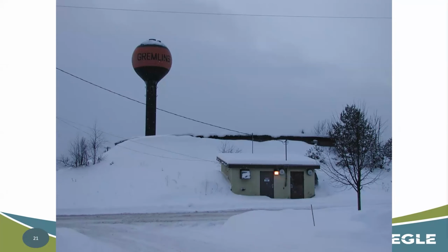Okay, so this is actually 2 combinations here. You have your elevated storage tank up here. This is a 50,000 gallon versus your 750,000 gallon right here. You can kind of see it, it's all covered in snow, obviously, but this is kind of doing the best of both worlds here. So it's maintaining that pressure if need be, but then you also have a large volume there if you ever need to meet those peak demands, or maybe you have a fire situation, things like that. That runs off this ground storage, which is actually run off of booster pumps. Okay, so it's actually feeding that to the system.